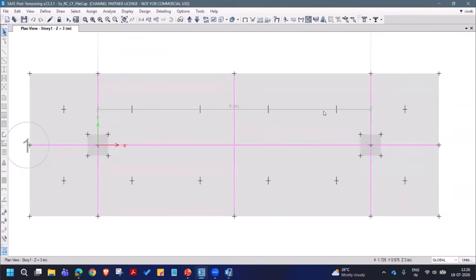In those locations, maybe if it is a larger pile cap, then you can also draw strips over the piles where you expect the reinforcements at the top, which will also be given in detail depending on how the strips are drawn. So drawing the strips is arbitrary. Typically, the strip width used is 1 to 2 times the thickness on the left and on the right.